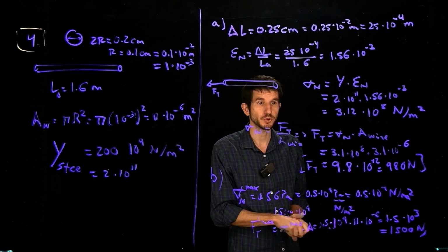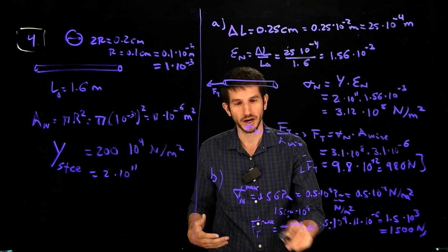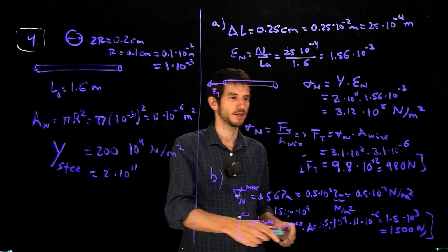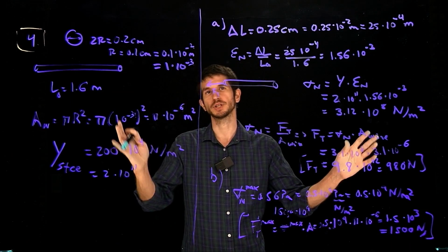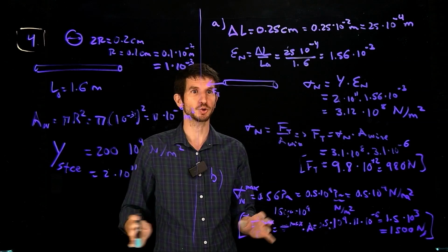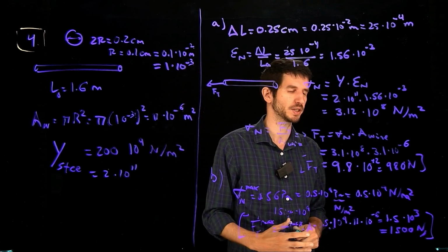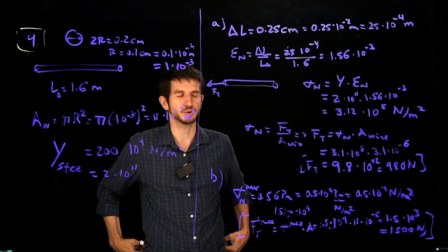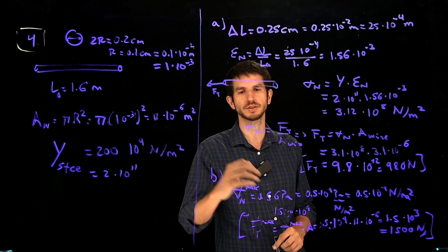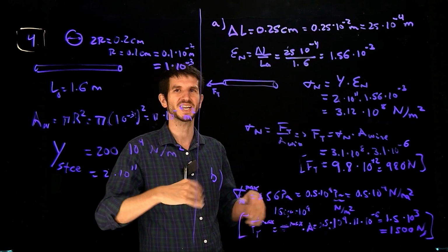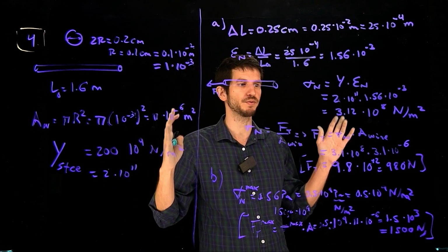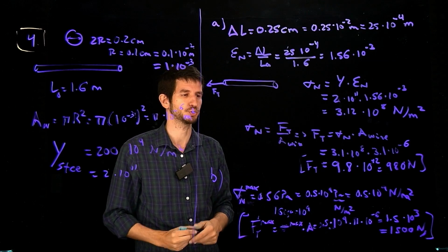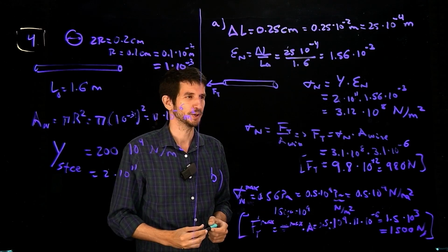So we're about 2/3 into the 1500 newtons. That means that we are safe to use this. However, how safe you are is actually a matter of design. Engineers never say, oh, the maximum stress is 1500 newtons, so we can apply 1400 newtons. Nobody would put their life into that sort of calculation because there are many simplifications and many things that can go wrong. So usually engineers use what they call a safety factor, which might be, if this is the maximum tensile stress, maybe let's assume instead of this, half of it, or a 10th, or a 4th, or a 5th, or something. So in case we made some errors, we are still far away from the dangerous area, okay? But that's a matter of prudence, nothing more.